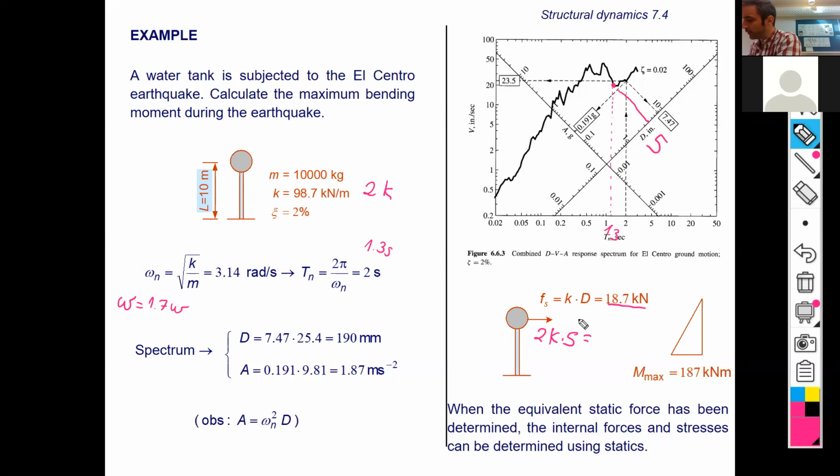But we are reducing the displacement from 7 to 5, which is not half, it's more than half, while we're doubling the structure. So if I make that structure stiffer, I'm going to end up with higher bending moments. So it's not obvious that just by making it stiffer is going to be better for the structure. Sometimes the optimal thing to do from the point of view of earthquake resistance is to make it less stiff. It depends a lot.